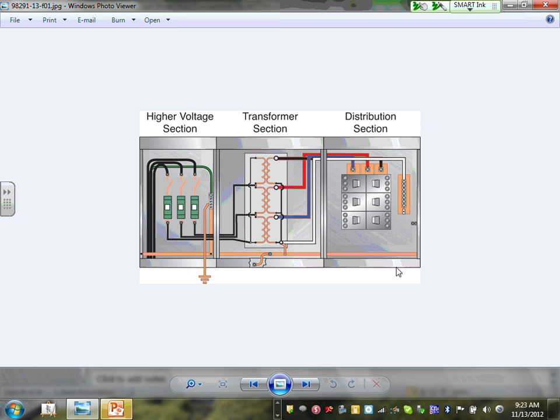I hope before you graduate from Dunwoody, you will know how the system is put together. Also, Jeff, I know you guys know it, but it gives you different options. Defining what a service conductor is, service lateral. You got to understand these. Can't believe when we start estimating, the students will come say, Chad, what type of conduit you're going to be bringing from here to this? Why do you care about this? That's owned and operated by the utilities. You know what I mean? So you have to understand where the service point is located. Service point. Very, very big deal.